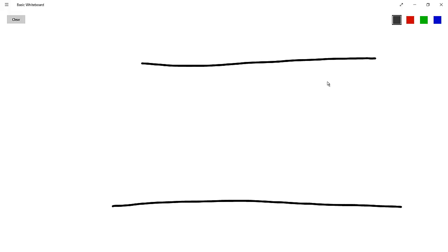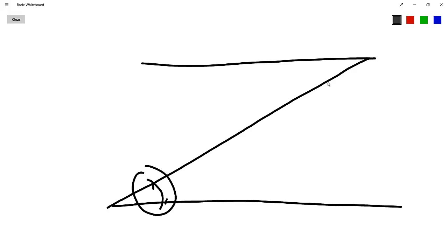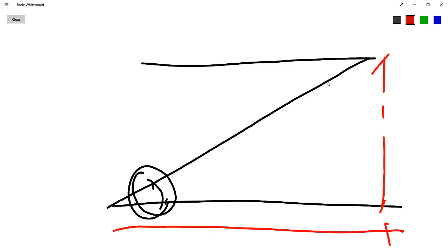If we have two levels like this and we want to connect them with a ramp, the ramp is something like this. The slope of the ramp should be able to deliver people from place to place, or maybe cars or whatever. The angle of the slope is different depending on the function. We never calculate the angle, it is very hard, but we calculate the slope ratio. The slope ratio will be, for example, x to y, which is the height to the distance.